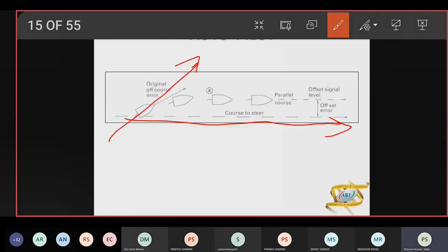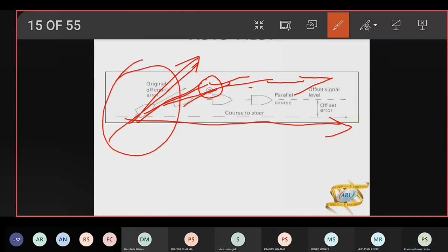It had gone off course, initial part proportional, then as she is turning like this, at this point midship, the vessel keeps on swinging, and then finally she comes and settles on the course. So this is the result of the derivative control and proportional control combined together.